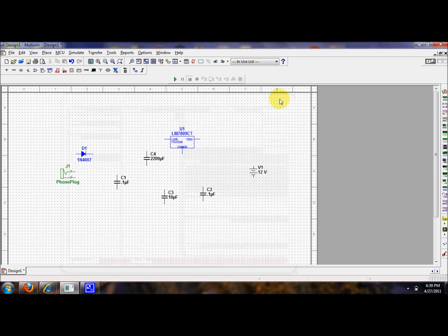Okay, next you want to close out of this. Put the 2200 UF first. Okay, put it right there. The 0.1 UF second. Put another 0.1 UF for third, and the 10 UF last. In order, like how it is in the picture.